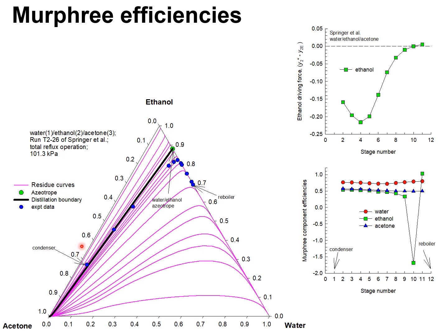From the experimental data for the various trays, the driving forces can be determined, and the Murphree component efficiencies can be calculated using the experimental data on the measured composition entering and leaving the tray, and the vapor liquid equilibrium thermodynamics that were determined using the NRTL model and the Dechema database for the experimental data.